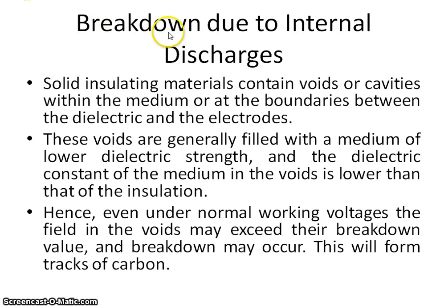Now the breakdown due to internal discharge. Because of internal discharge, the breakdown will occur in the insulating material. Solid insulating material contains voids and cavities within the medium or at the boundaries between the dielectric and the electrodes, so that the gap is filled with air. These voids are generally filled with a medium of lower dielectric strength, that is air, and the dielectric constant of the medium in the void is lower than that of the insulating material.